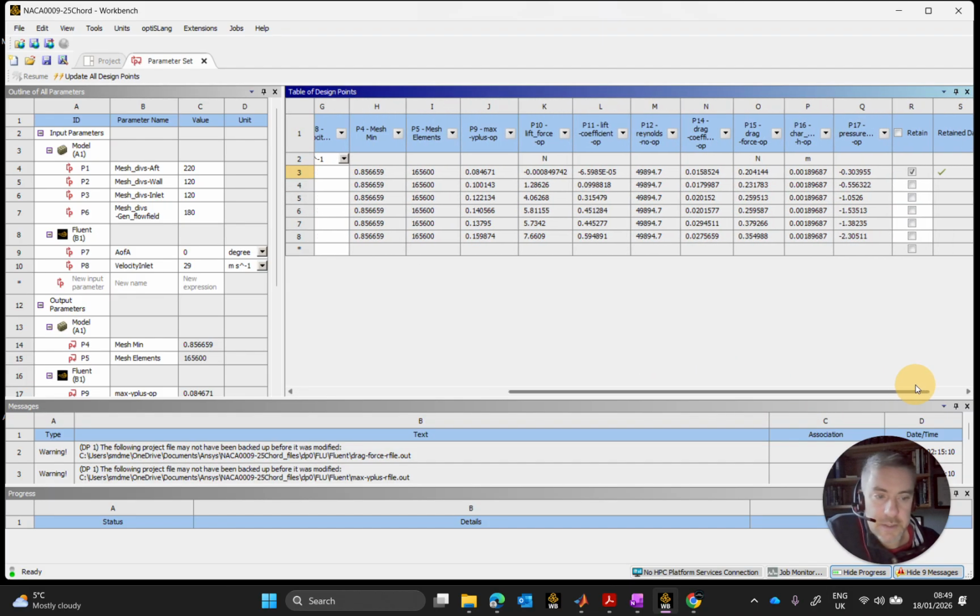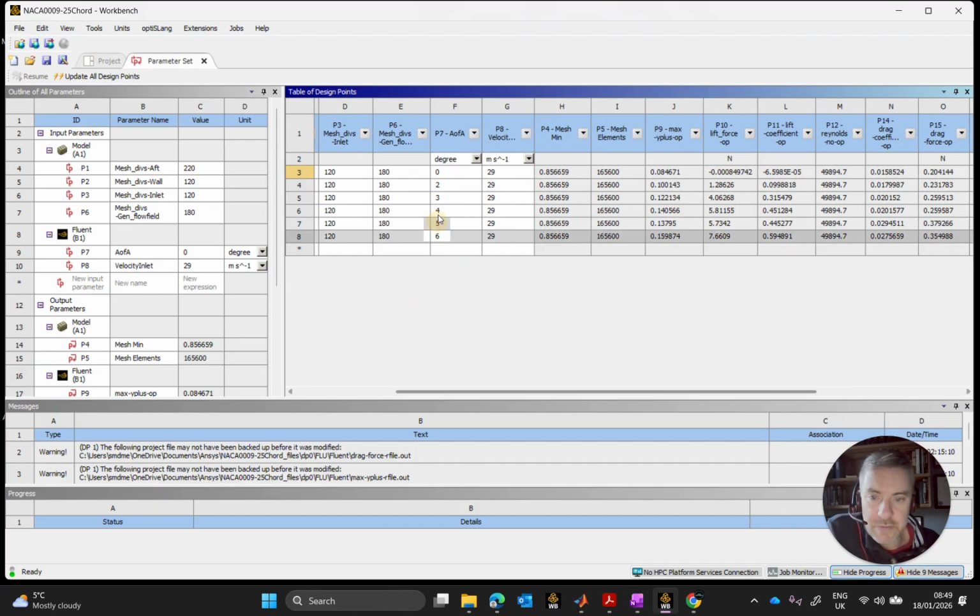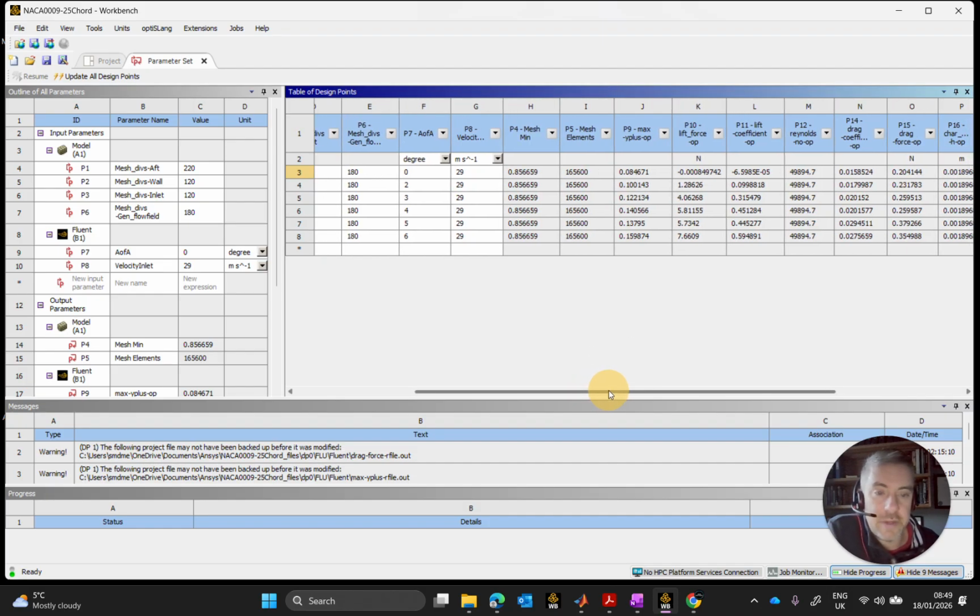I think the point has been made what this is for. So you increase a variable, just one variable, don't increase more than one, okay, because that's the worst thing you can do in CFD: change a couple of things, rerun it, then it comes out right, or appears to be right, and you say, right, what was it that made it right? You know, was it this thing that changed or that thing that changed? And you can't pin it down. So you make one change, run it. If it works, that's the change that caused the improvement. If it didn't work, no, we'll put it back to the way it was, make another change. Okay, and mark it. That's it. You have to do one at a time. It has to be completely iterative till you find what's wrong.